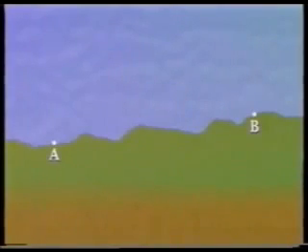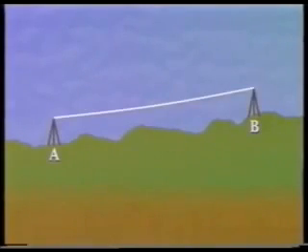In cases where the ground surface is very uneven, or where high accuracy is required, the tape can be suspended between two supports to form a catenary curve. However, the use of tapes in catenary is very unusual nowadays, and, if done, is restricted to steel taping only. The length obtained is the length L along the curve formed by the tape.